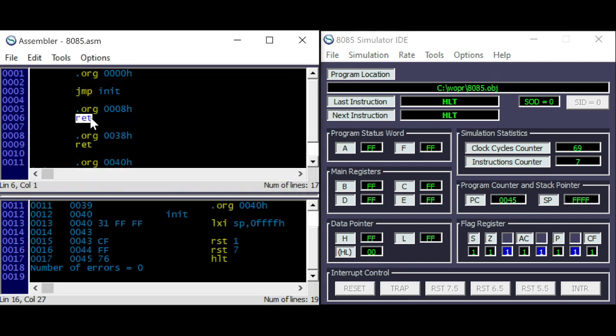Normally you won't have a return here, but a jump to your interrupt function, because there's not enough space here for a program. The next interrupt entry point would be 10, and that is only 8 bytes away.